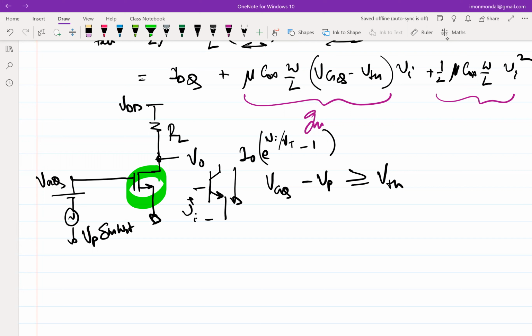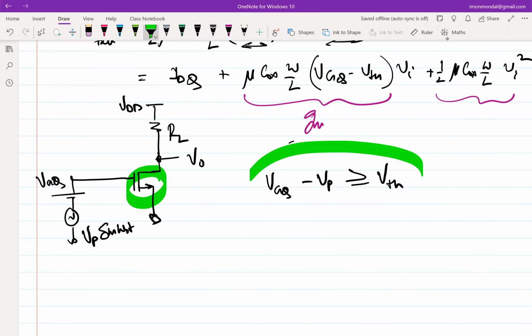Similarly, in case of MOSFET also, it's not as if when you go to VGS equal to VT, suddenly the device is not working. It stops working reliably much before you go to absolute zero. So that is why we will not use this constraint. The constraint that we will be using is again the same thing that we talked about 2 minutes back, and we'll essentially say that the lower limit of the input voltage is determined when total output current, or total drain current